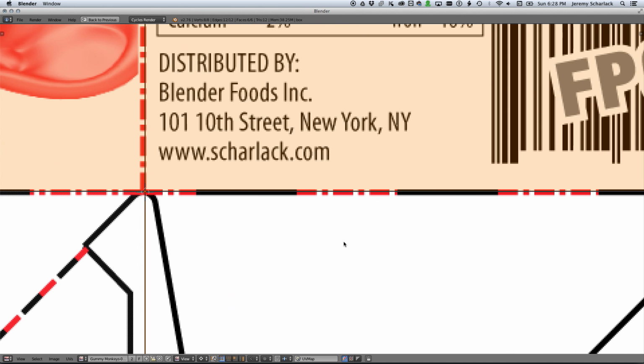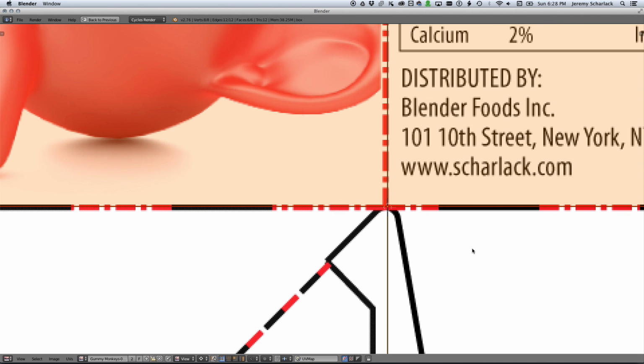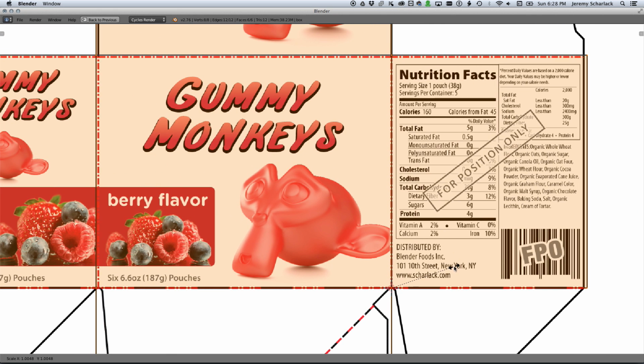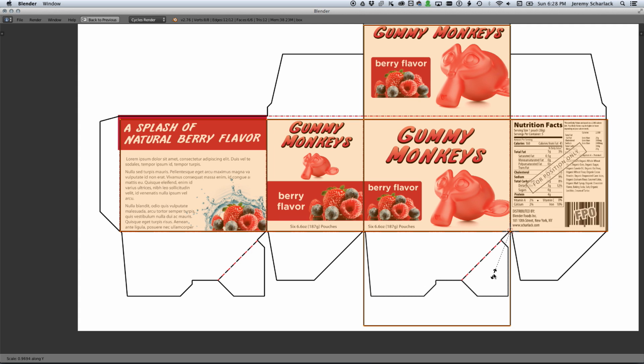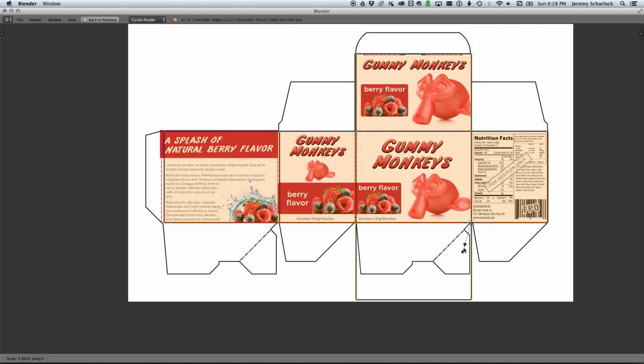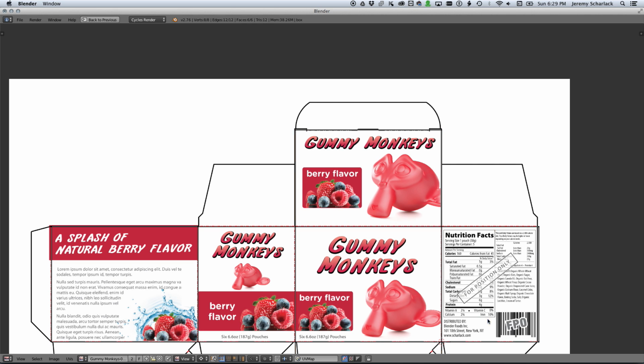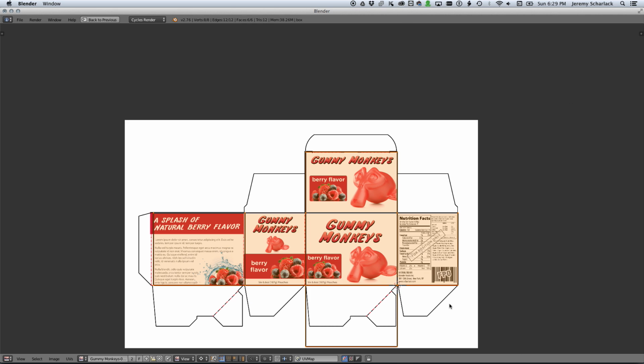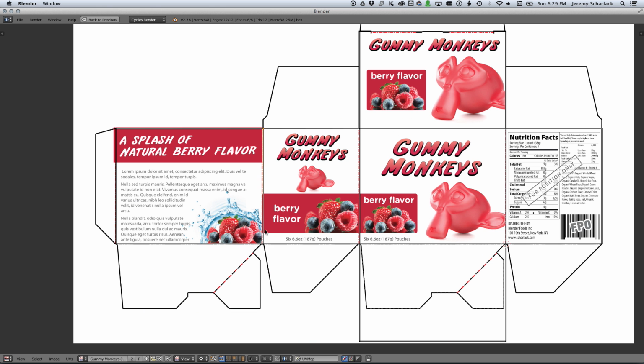And you can zoom pretty far in. No reason not to get this actually pretty exact, because why not? So now I'm tweaking it, getting it exactly right, but I'm just going to speed right through it so you don't have to see all the intricacies. But you just want to scale. Sometimes you have to scale in the X direction, sometimes in the Y direction. And you do that by hitting SX or SY, and so you just scale in one direction.